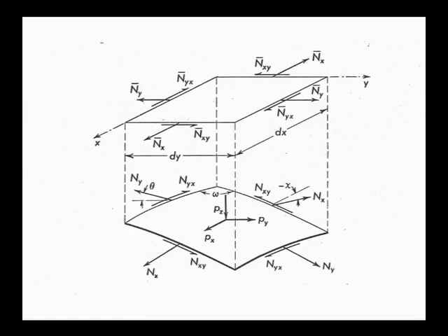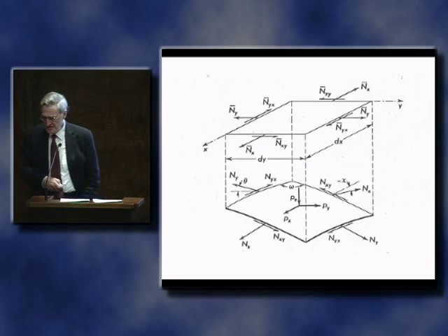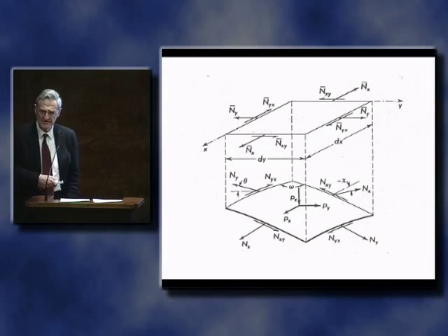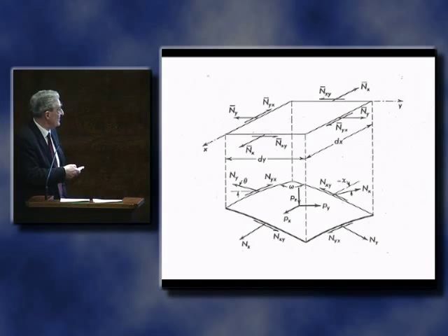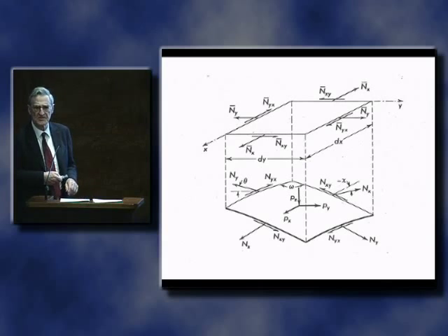And assign forces. And this is where we're beginning to make some severe assumptions in our engineering analysis of this particular structure. These P's represent the weight, the forces acting on this little element. This is evidently the self-weight. This might be perhaps due to wind or something like that. In general, there will be 3 components of force there. They need not worry us, they need not come in.